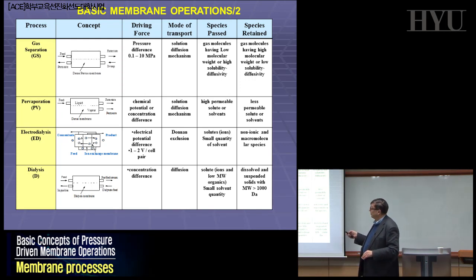So here the chemistry is quite important, while there it is not important at all in first approximation. It's important for the fouling and interfacial phenomena, not for the mass transfer. Theoretically, if you make your simulation and you don't assume any polarization, etc., chemistry does not appear in microfiltration or ultrafiltration. It is essential here. The interaction between the penetrants and the material is the core of the system.